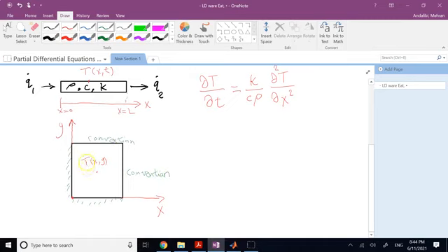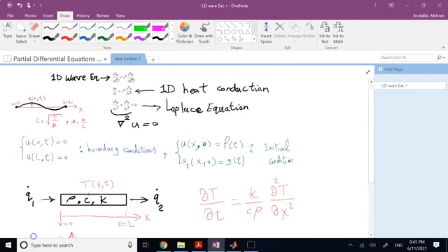So it means the partial derivative of T with respect to x here and the partial derivative of T with respect to y here are 0. So there is no heat influx in or out. And here the heat coming from the conduction is equal to the heat taken out by the convection, right? So I don't want to get into heat transfer right now, but if you can see here, depending on the initial temperature that you gave to these different points, how you heat it up at time t0, there is a right-hand side here, okay?